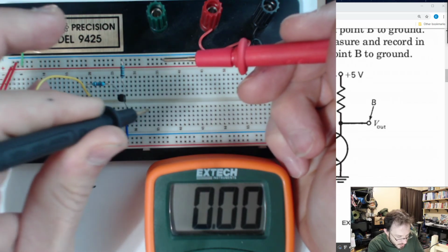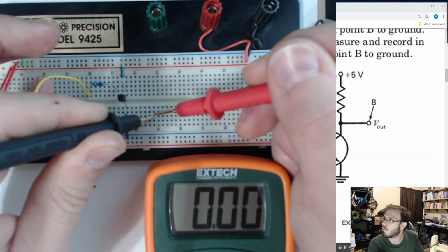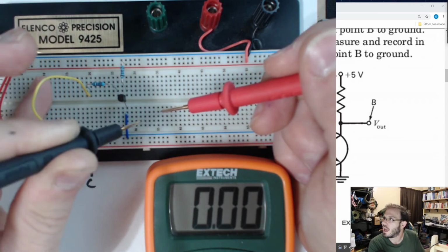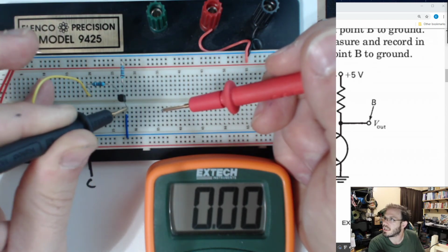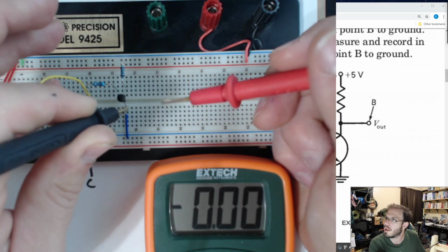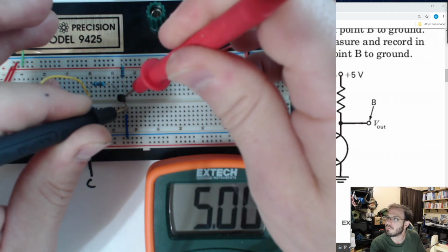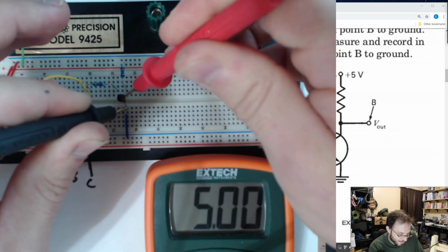Now, you can't just do this on an empty row of 5 because you have plastic insulating your probe from the connectors that are below. However, when you have a conductor sticking out of it, it makes a great place to hold the tip of your probe so that you can go ahead and do the same thing with the other probe and very easily measure, look at that, 5 volts.